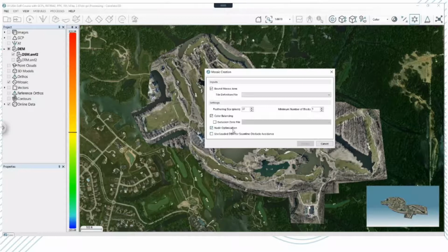I use it a lot, especially for a lot of UAV projects. It does help a lot. It does take the best nadir portion of that image and then produces the best results in the Mosaic. I see it also helps a lot with the seamline editing. They're tools that sometimes you overlook because you're just hitting the process and you don't really think about the benefits of it. But I always, especially for large projects, I always decide to include it. I use it myself a lot.